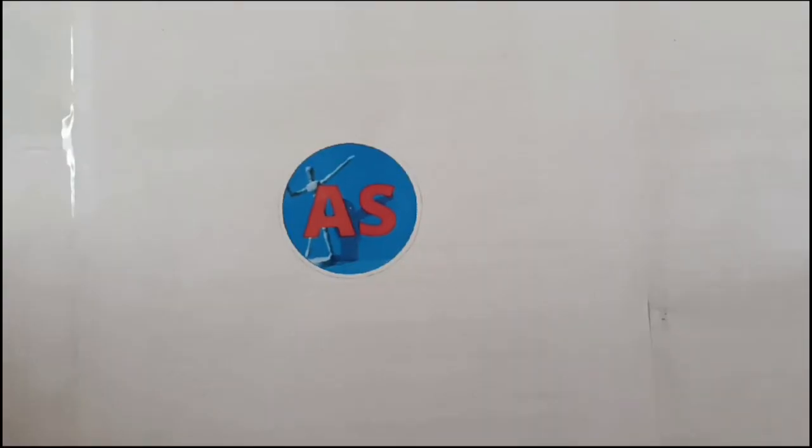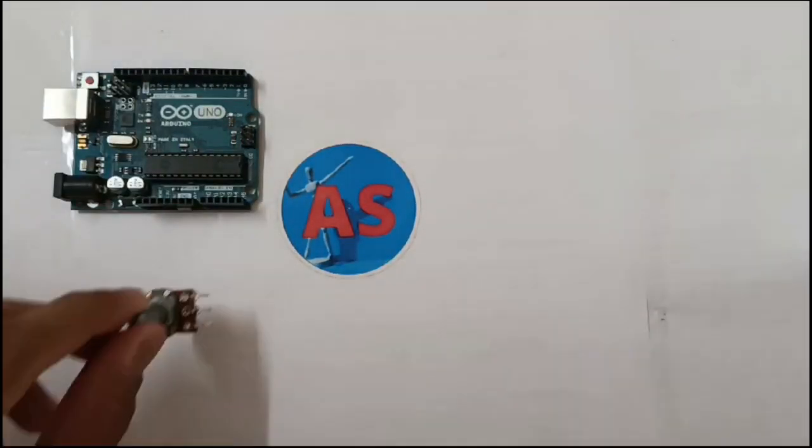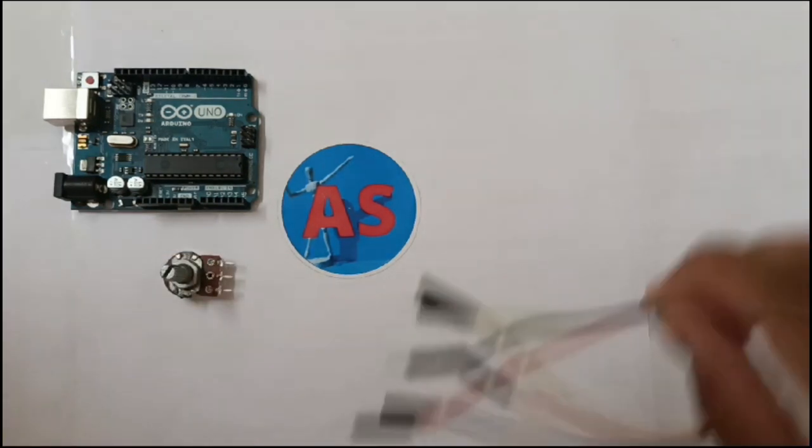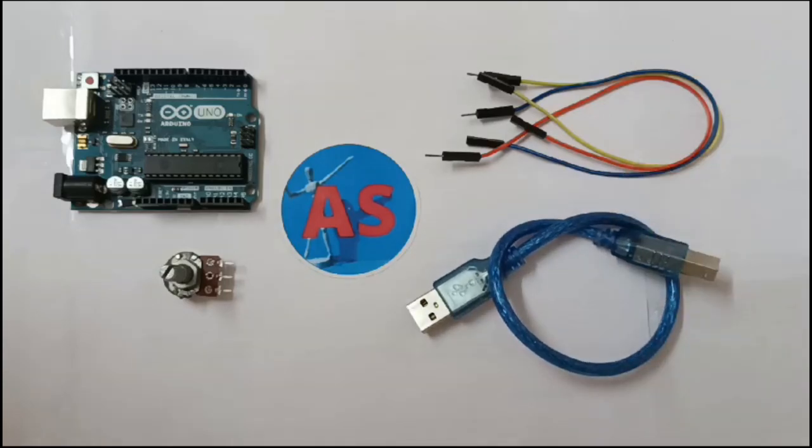Hello, welcome to my new video, and in this video we are going to derive the coordinates of a 10 kilo ohm potentiometer by connecting it to analog pins of Arduino. These coordinates, when defined in a range, can be used to control and regulate various modules like LED displays, motors, display boards, etc. The components of the circuit are one Arduino Uno R3 board, one 10 kilo ohm potentiometer, 3 jumper wires, and one Arduino Uno cable.